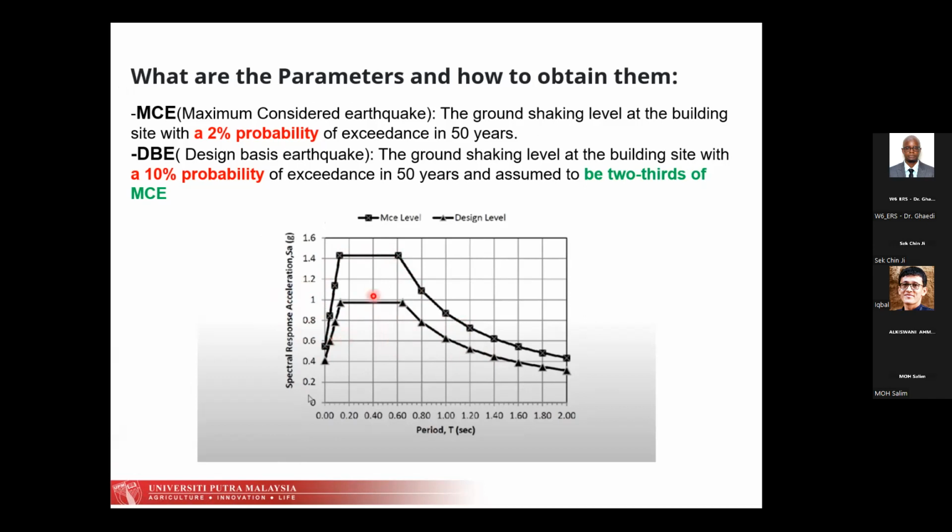It's more economical. And as we see, there is a chance that in real life an earthquake will happen that exceeds this earthquake. And this is what makes this field interesting, because a structural engineer should be able to understand that the code is giving the minimum requirement. Usually when we design in statics, we take the critical case, the maximum, but in the case of seismic design, it's not always this case.